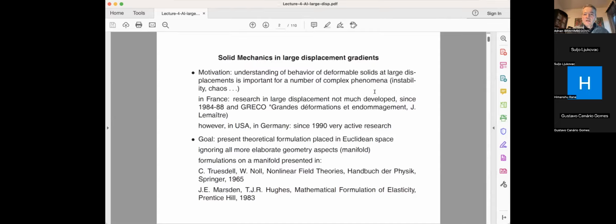So, for example, taking wind load and things like that is certainly of big importance, and you have very large displacement, large rotation. Then also in the technology of many types of products, you want to look into large displacement, large rotation, and especially failure phenomena, localized structure failure, which in fact is really often related to this type of thing. And I showed you last time that you can take a cohesive length to be a geometrically nonlinear beam, so you can handle these local large rotations and stuff like that.